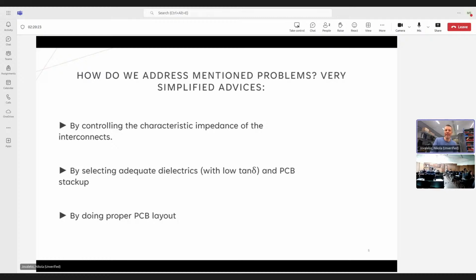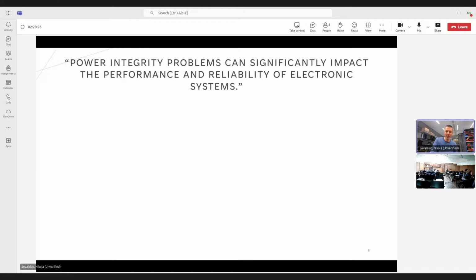Now about the power integrity. Does anyone know what power integrity means and how that influences the design? You should have a constant power value around all your PCB, taking into account the power drain from different devices, because that could make a slight voltage drop from one point to another of the PCB, and a component is not fed with the correct voltage.